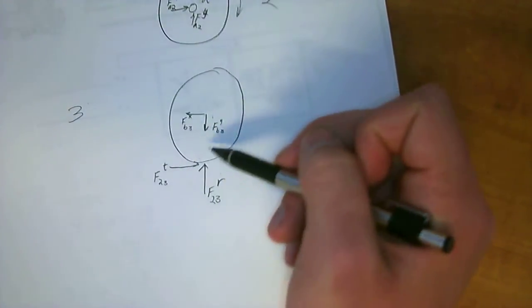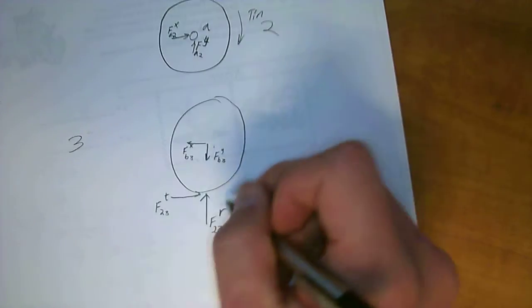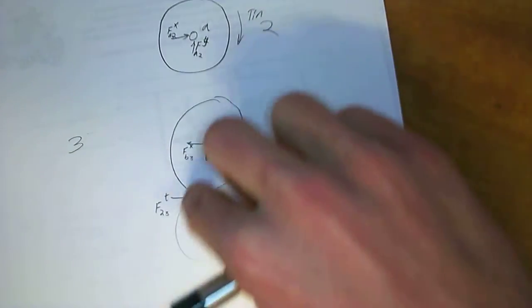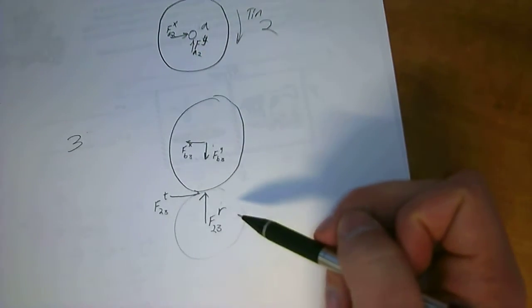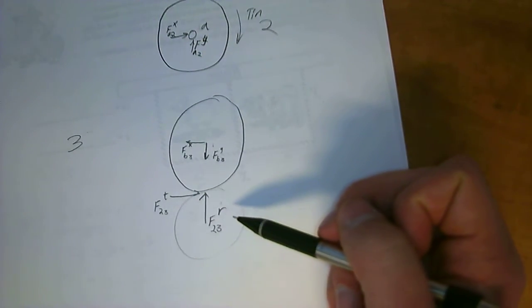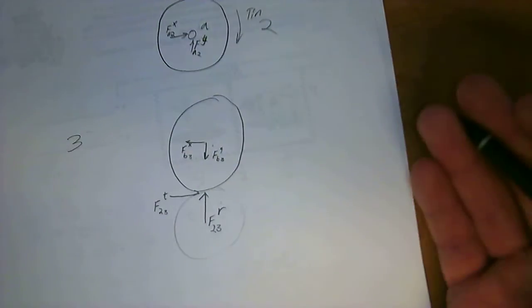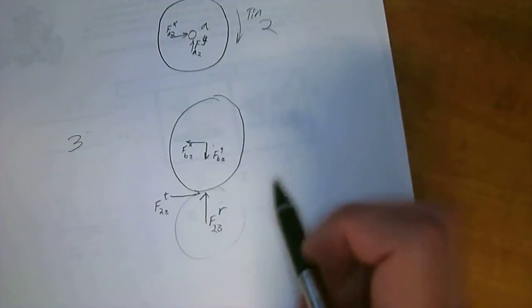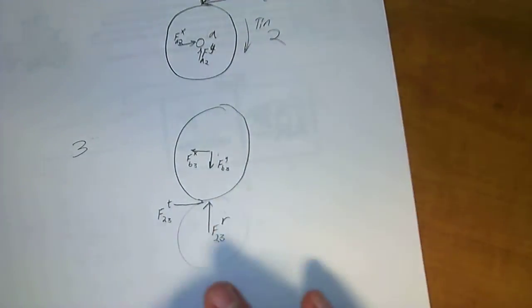These are the forces actually being applied by this gear spinning around and spinning this gear. So you can imagine if this gear is down right here, it's spinning at this rate, so it's applying a force right there and a force inward. Most of the time, the radial forces you almost ignore, but you want to draw them anyway just in case you ever have a special system. But in a good gear system, there shouldn't really be much of a radial force in this position.